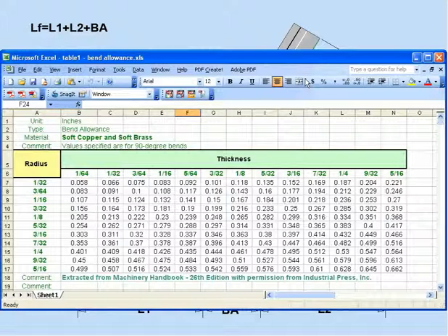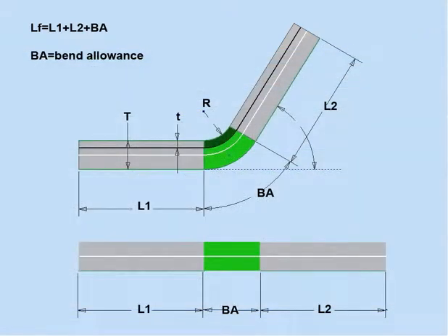The bend table approach to calculating bend allowance is probably the most accurate method because you can input the data manually. If you're not sure of the bend allowance value, you can always run tests. For example, take a piece of scrap metal that you'd be using for this part, identical to what you'll be using for the machining. Then you bend it using the identical process that you'll use during machining. Then you'd take your measurements before bending and after bending. Based on this information, you'd adjust the bend allowance as needed.